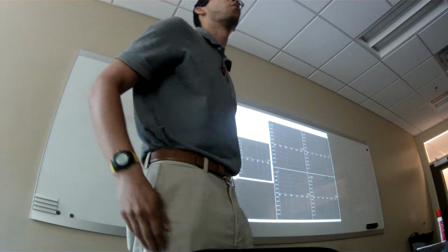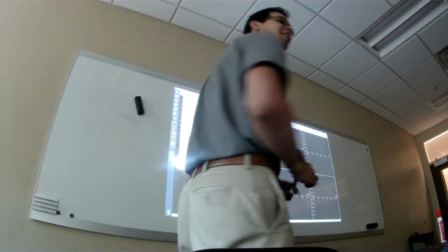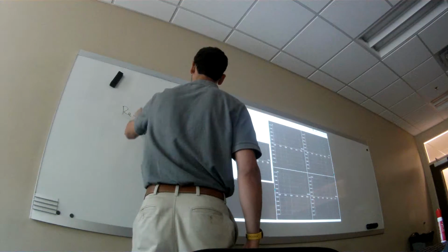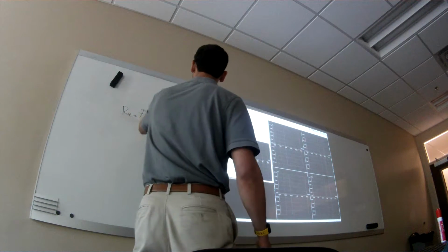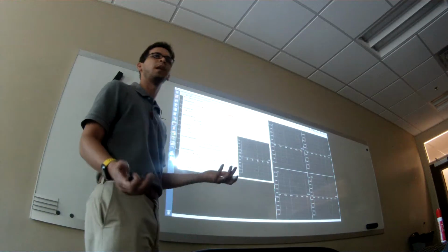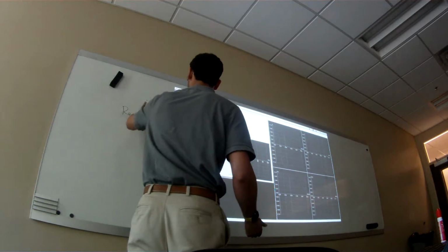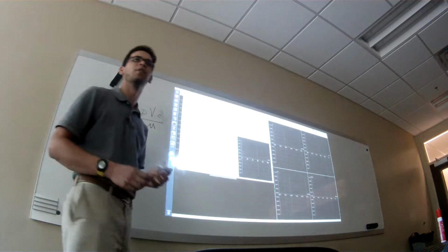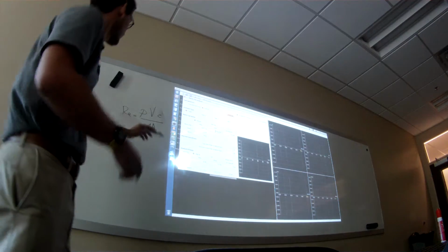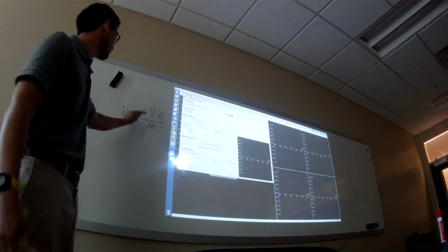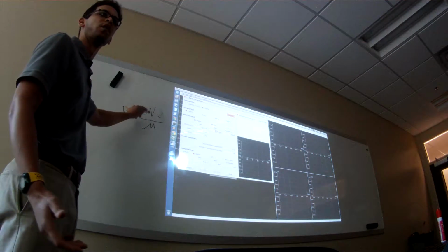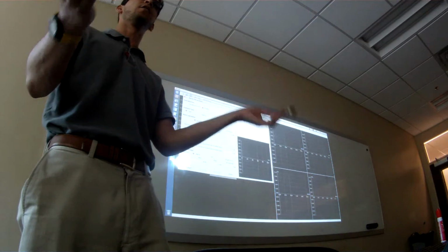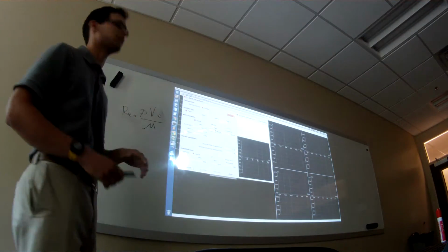There is this thing called Reynolds number. So many things, right? Reynolds number is equal to the density of the air, the velocity of the aircraft, some unit length. People like to use the chord length sometimes, so I'm just going to replace that with V and C, divided by the viscosity of the air. Viscosity of the air is relatively constant. Density of the air is relatively constant. So the only thing you can change is V and C. If you're the same aircraft and your chord is constant, the only thing you can really change is V.